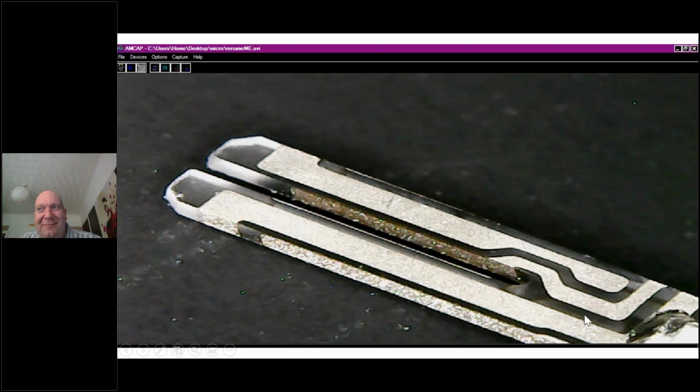So the thing's oscillating, it's making a current, and as long as I empty an energy store somewhere else, then I'm going to be able to put that energy into this system and keep this thing going. So that's why your quartz watch has a battery. It's got nothing to do with keeping time, as well, in the sense that it keeps this feedback loop going.